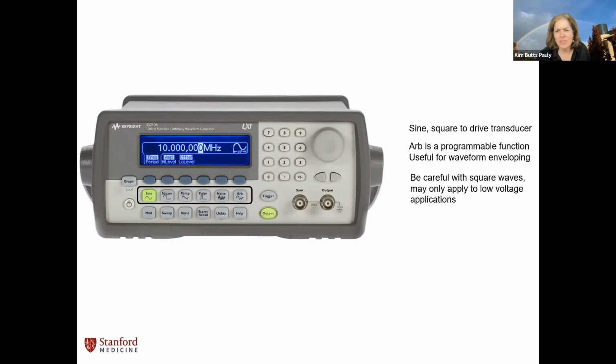Do you use it for the fundamental, or for an envelope across the fundamental? That's right. We're not using it for the fundamental because that's so well defined by just a sine wave. But you might use the arbitrary, and we'll get to this in a bit, to modulate or give your waveform a slow rise or slow decay by multiplying the two together.